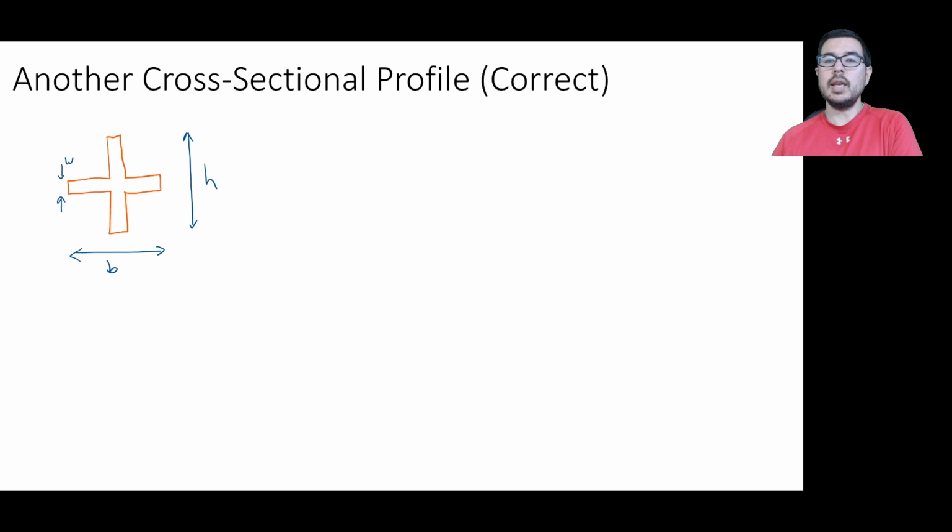Okay, we'll say that here we're going to make... and so the other way could have been corrected if we had added the appropriate A d squared terms. Here what we'll do is we'll say, okay, here's a horizontal beam, and then we don't have to do any d business here, because the centroid of this shape is on the z-axis, on the neutral axis.